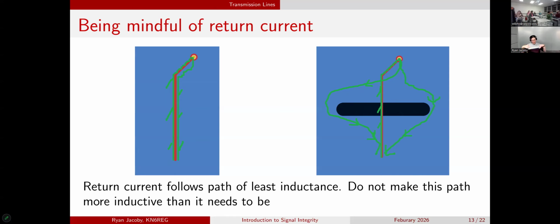Yes, when you add vias on the side of a trace, each one does have a small inductance to ground. Generally, when you have a lot of them together in parallel, that inductance gets really low, and it provides a very similar ground on the plane below and the plane next to your trace.